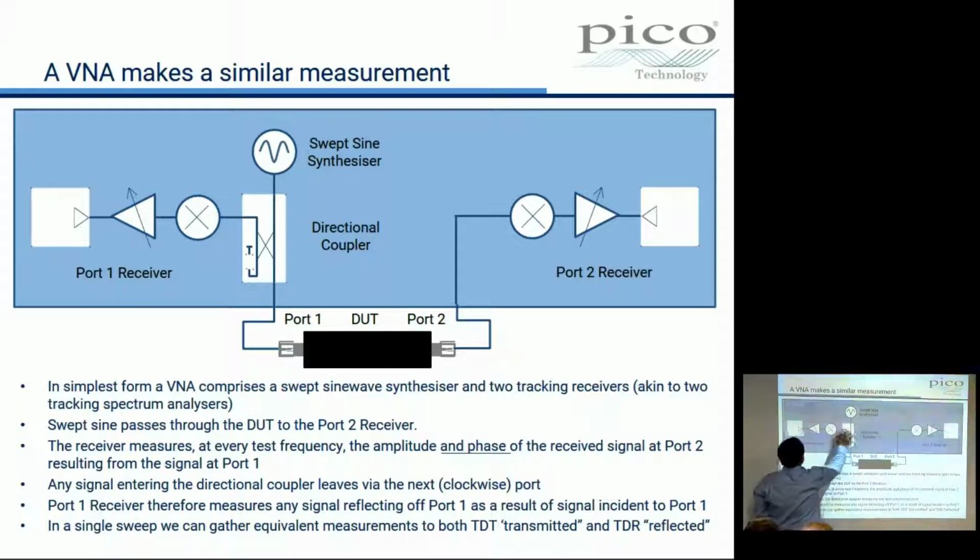What we're going to do then, we're going to pass it into a tuned receiver. It is basically an ADC. It's a variable gain amplifier, and it's a mixer. We'll say a little bit more about all of those, but basically it works like a tuning radio.